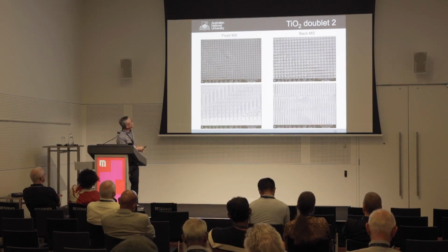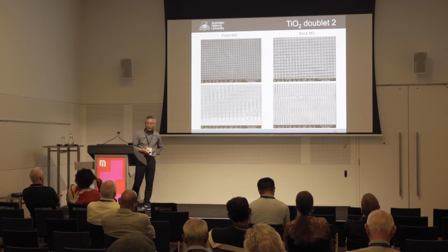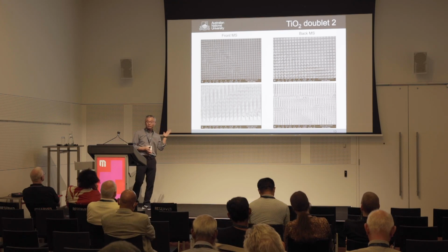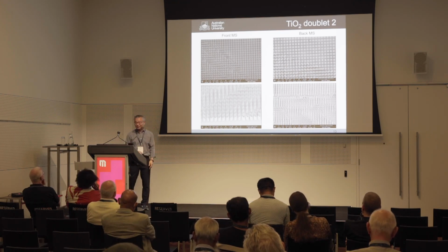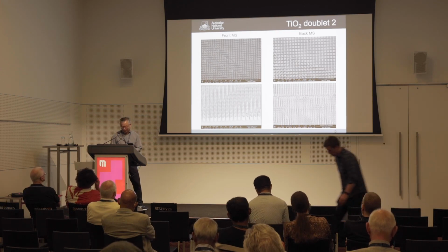And this is the front metal surface, top view, and this is a tilted view, and this is the back side. The height of this titanium dioxide is about 600 nanometer, and down to 100 nanometer it's quite stable, but below 100 nanometer, sometimes it falls over like this. So this is a stability issue in this small range.